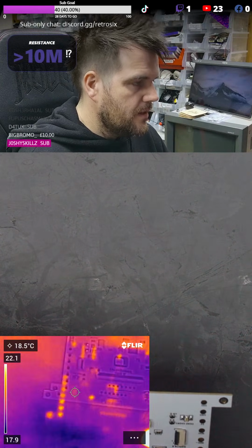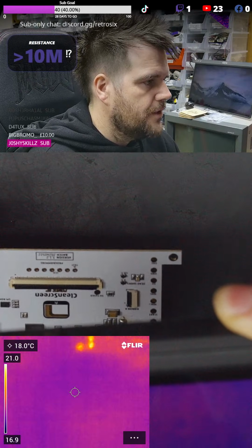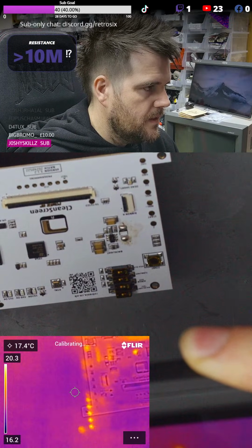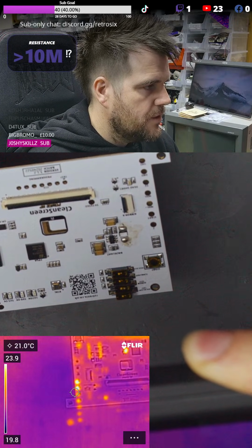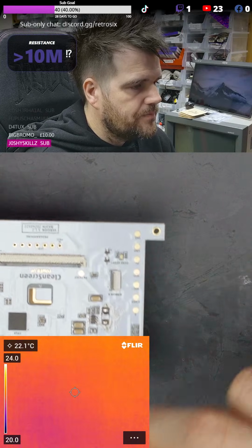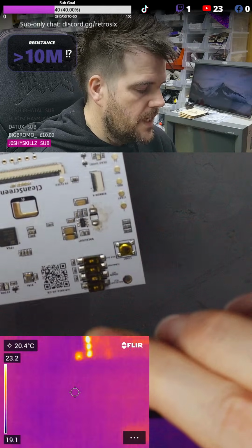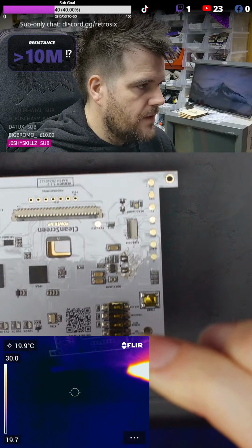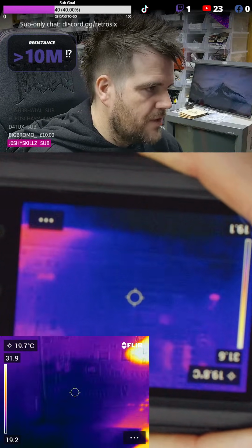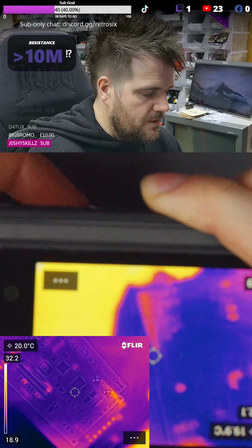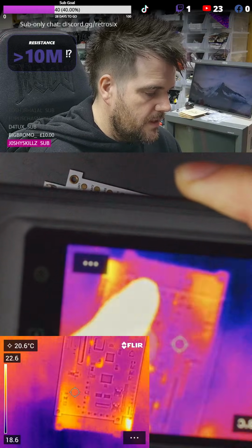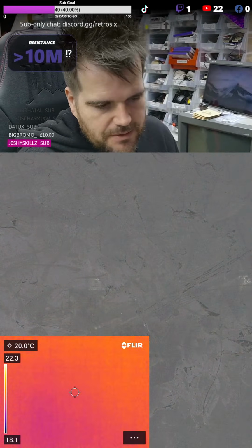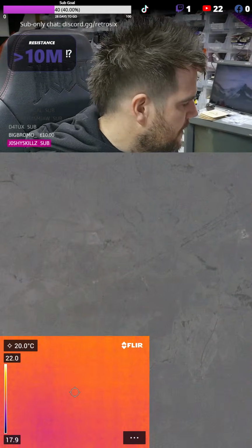See them dots there? The dots on the thermal are showing us if there's heat. See them dots? They are basically these pads here, and what this is, is reflection. Anything that's metallic and reflective, you can see if I twist the board, the dots move around. Obviously, this is not a super accurate thermal camera, but you can see the point: if you have anything reflective or metallic, it reflects radiated heat as well. So it looks like places are hot when they're not.